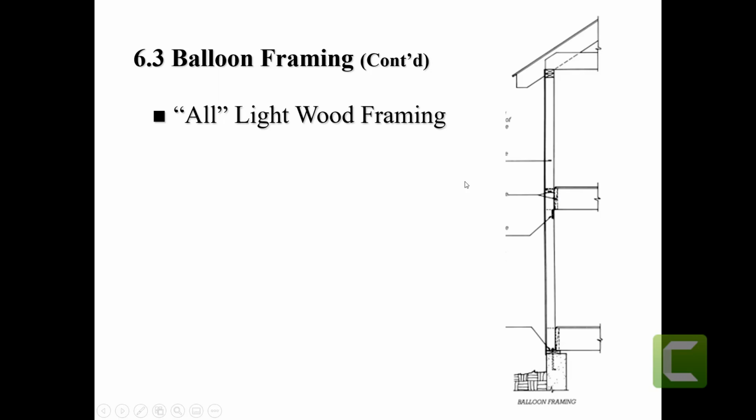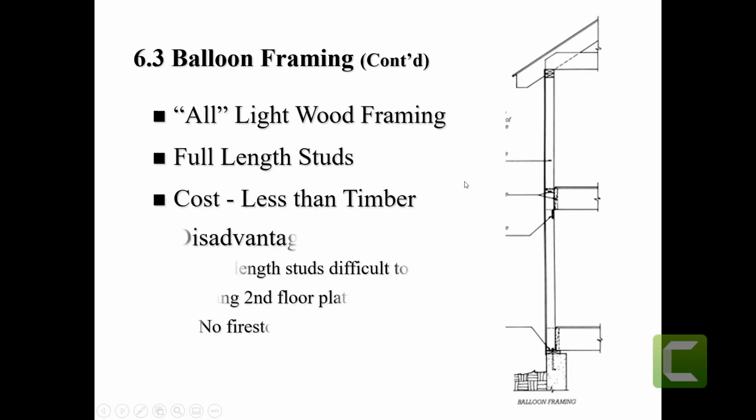Now, the disadvantages of having a full length stud is that first, you need lumber that length. Second, we don't even grow wood at that size. And typically, lumber at that length is far more expensive than shorter wood studs.